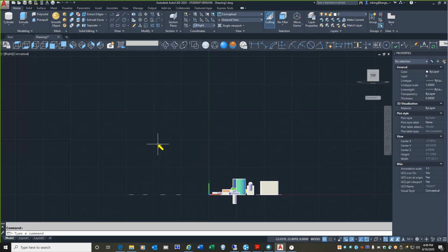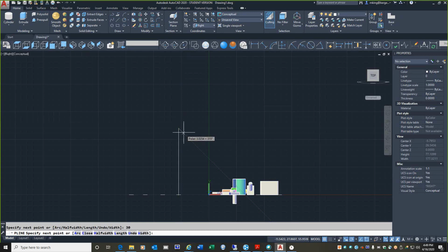So now go to polyline. Select polyline, right up here, upper left corner. And we're going to snap to the center of that rightmost circle. Now, even though we're looking at it from the edge, AutoCAD will know that it's a circle, and it'll grab the center of it. So go ahead and click right there. And then lift your mouse up. We're drawing a polyline, and let's say 30, as in 30 inches. 30, enter. So just line up from the center of the circle upwards 30 inches. Then move to the right, and let's say 20 inches. Okay, 20. So up 30, to the right 20.